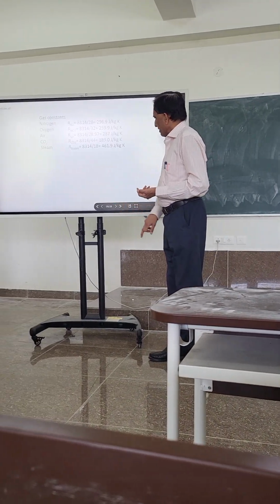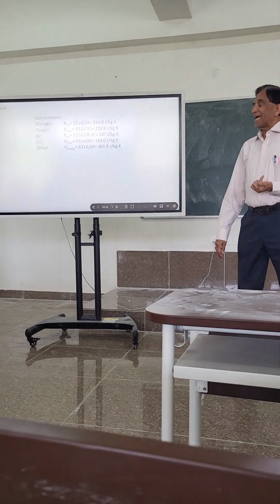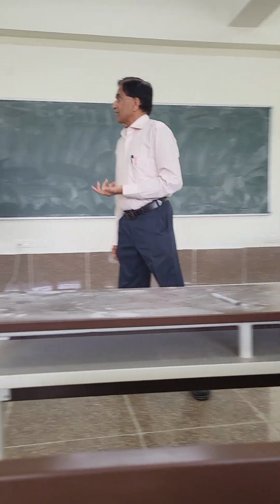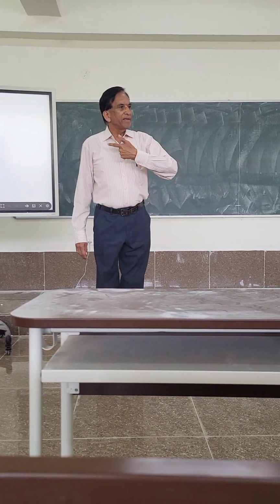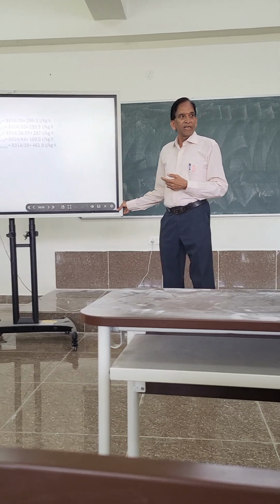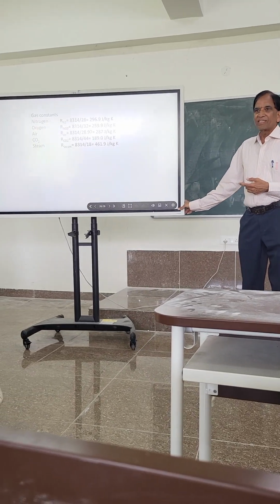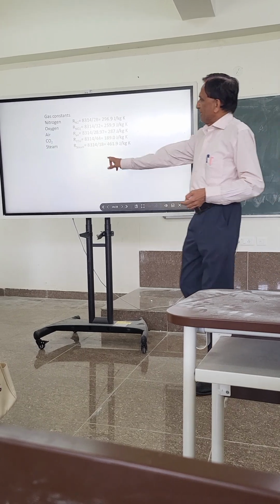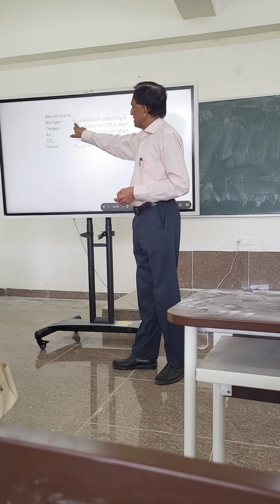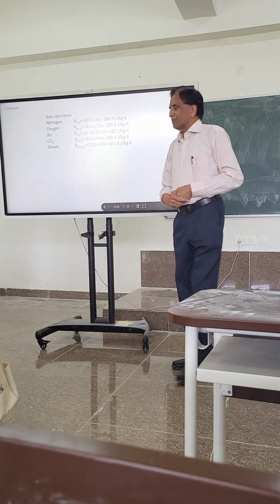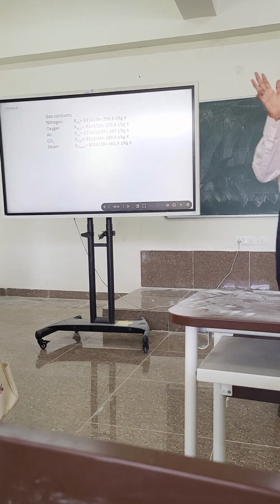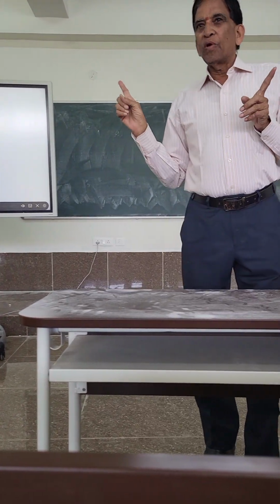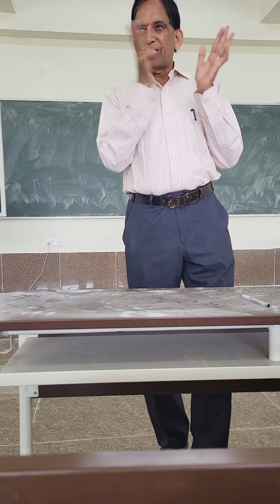On the other hand, if you want to find out the characteristic gas constants of each of these species of air, for example, this is what you get. Are you able to see? So this is the characteristic gas constant for nitrogen, 8314 divided by 28. 8314 is in joules per kilomole, because we use the word kilomole since the molecular weight is in kg per kilomole.